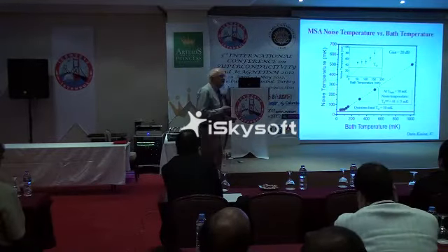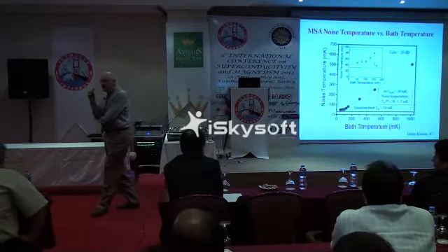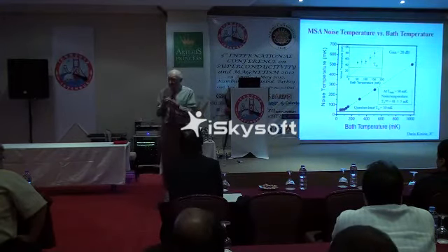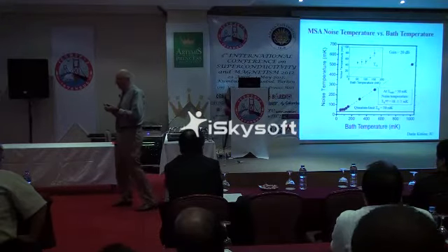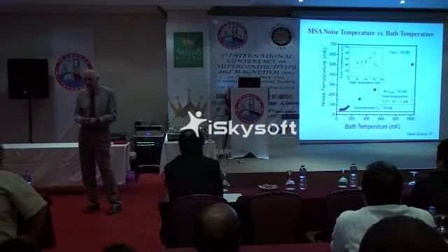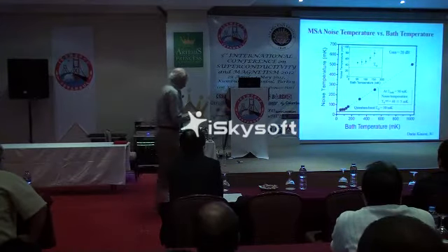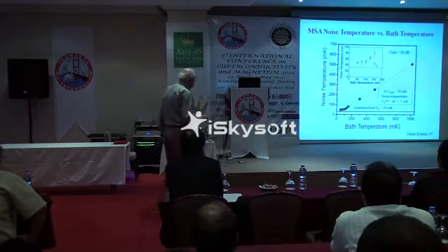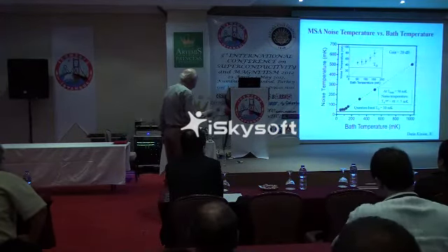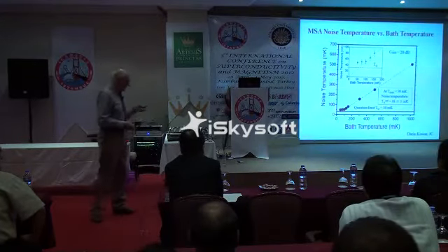Just as a quick comment on this result, you can say, why is it better than a HEMT? The thing about the HEMT is that because the power dissipated in it is quite large, the HEMT itself probably operates at around 20 Kelvin, no matter what the bath temperature. So as you lower the bath temperature, the noise temperature of the HEMT does not change significantly. On the other hand, in the case of the squid, because the dissipation is very minimal, then although there might be some small heating effects around 50 millikelvin, the fact is the temperature of the device keeps plummeting as you reduce the bath temperature.